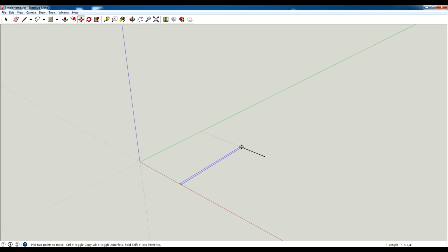So you can see that when I drag this left or right, or even up, this line that is attached to it is going to go with it. So I just want to copy this line to this side. So a shortcut for that is you can hit Control when you're using Move after you've selected something, and it's going to make a copy.